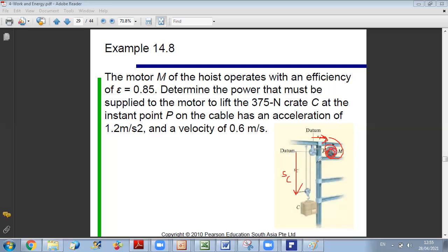So now the total length of our cord will be equal to, so we have SC constant here plus SC, so 2SC is another constant. We have here also a constant. So all constants can be lumped together, plus what is going inside the motor, so plus SP. So the relation I can write for the cord is 2SC plus SP equals a constant.